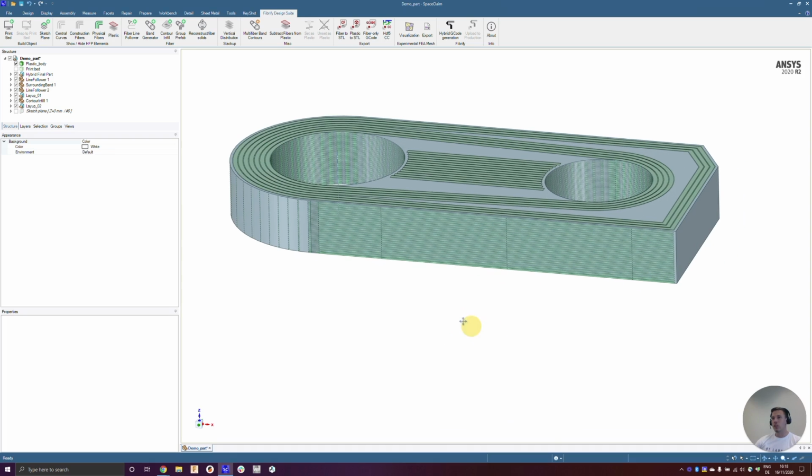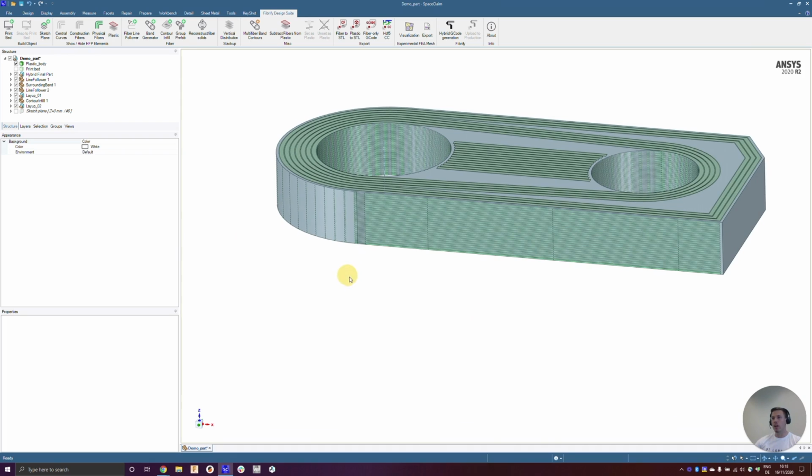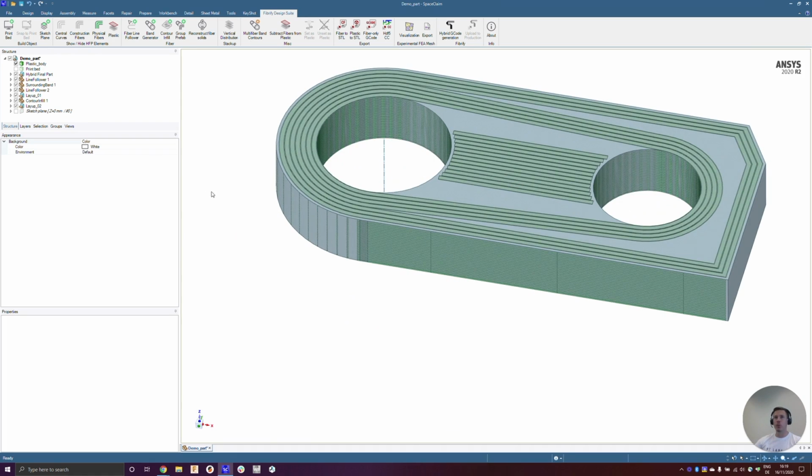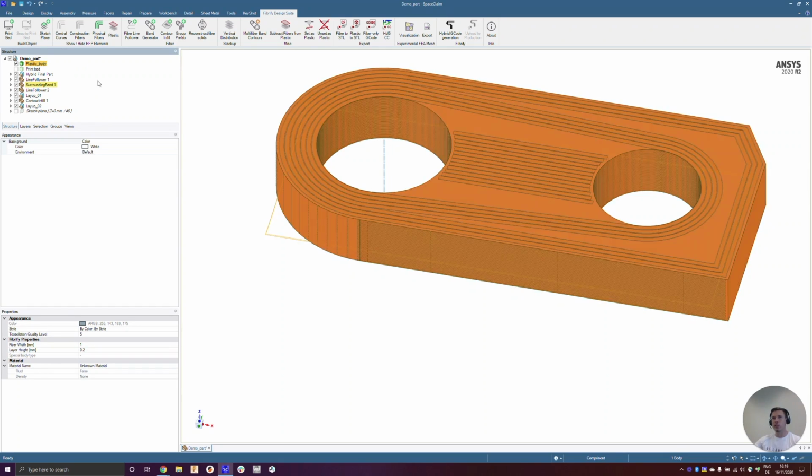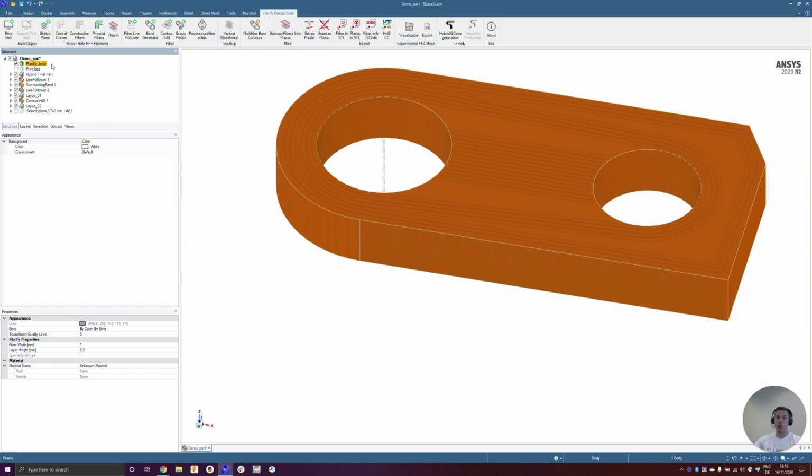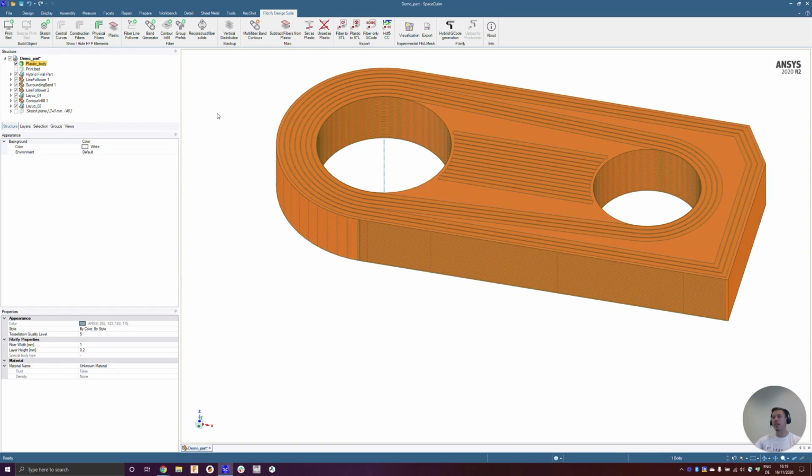So to quickly show you this and to actually prepare the final model for export, what we have to do is select our base geometry, which is in our case already called plastic body. We can then go to the MISC category here in the Fibrify Design Suite ribbon and set it as plastic.